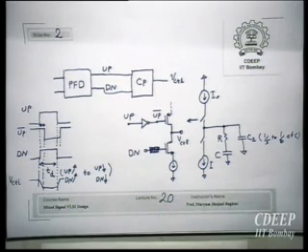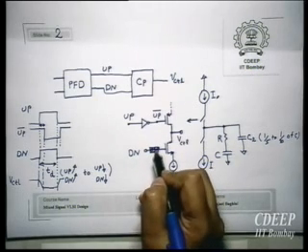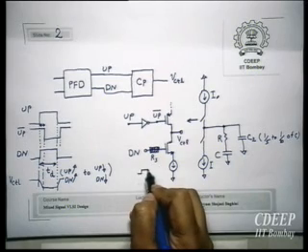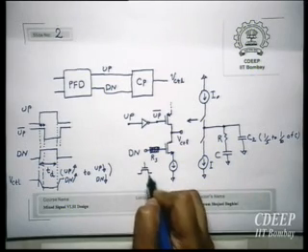Or putting a small resistor here. Effectively it is like that. I am putting a small resistor here. So this series R, which can be simply like a transmission gate, will avoid this problem.